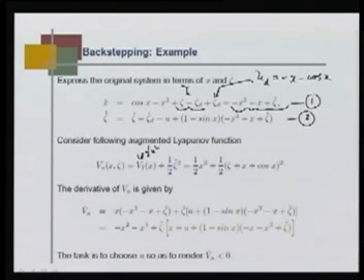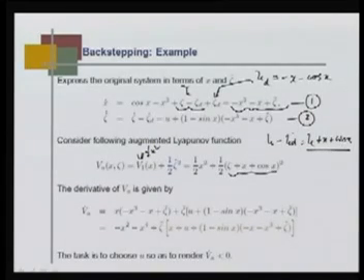half x square plus half xi tilde square. So, this V1(x), half x square plus half xi tilde square, can be written as (xi plus x plus cos x) whole square. Because xi d is minus x minus cos x, xi minus xi d is xi plus x plus cos x. So this is what is put here, xi plus x plus cos x whole square.